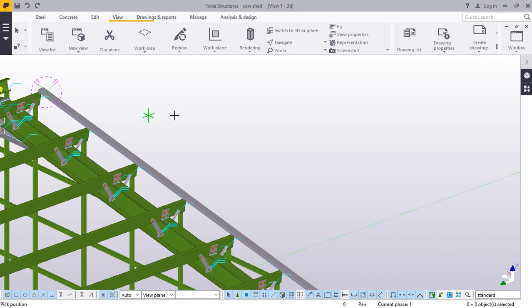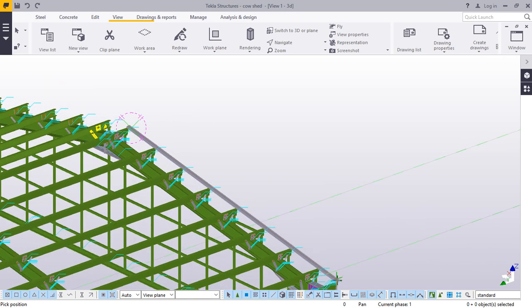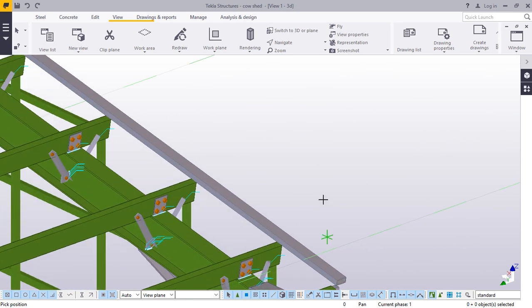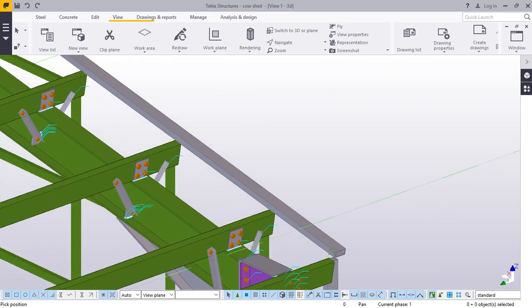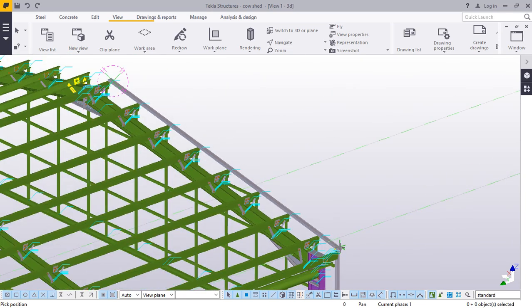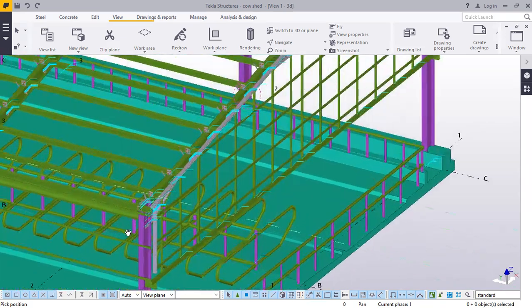You just click on that end and click on this end. You'll be able to create a steel profile that will assist you in trimming off the sheets once it has been placed, to take the profile and the slope of the roof. It's very important prior to placing the iron sheets.